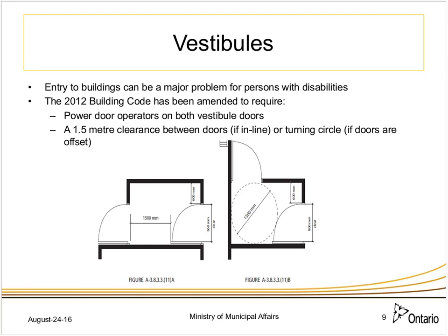While I'm thinking of wheelchairs, one of the things I'd like to point out is when we did this exercise, the wheeled device that we paid attention to was only a manual wheelchair, not a scooter. I repeat, a manual wheelchair, not a scooter. The building code does not make allowance for scooters, only a wheelchair. So that's why you see the 1.5 meter turning radius.